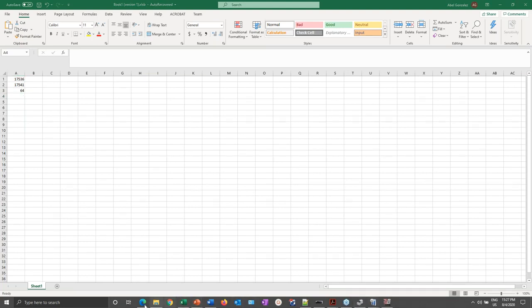Now, in RTMS, whenever we read the settings, we're reading the settings of the active group that's enabled in the relay at that point in time. Let's say, for example, you have active group number 1, and that's your normal everyday settings.